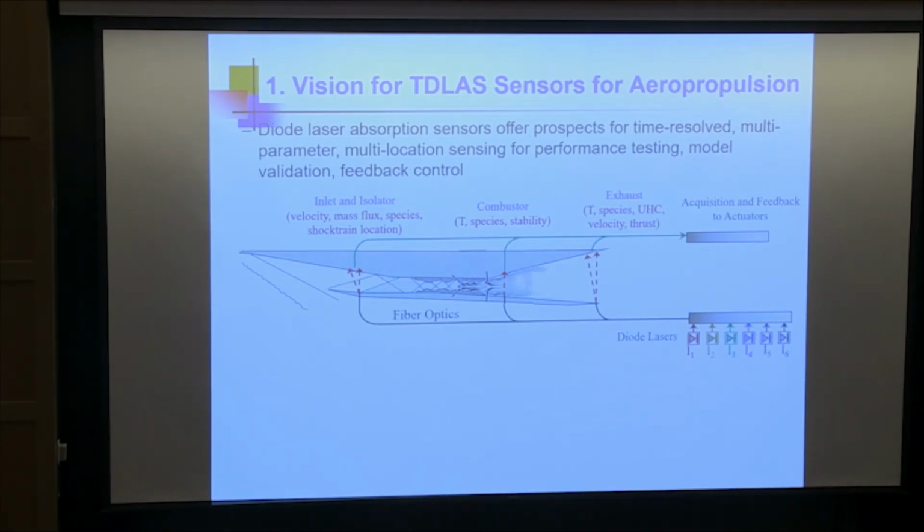and we could probe different parts of a scramjet combustor. The inlet: propulsion engineers want to know how much air is in, how much fuel goes in, how much thrust you get. That's what they want to know, which means how well they burned the fuel. So you might care about the temperature. Propulsion people care about how much air is coming in, what's coming out, what's happening inside. If you probe a few of these species and you accept the line of sight measurement, which is a path integral, you can learn what you need to learn about these devices: temperature, velocity, water, CO2, and so on.